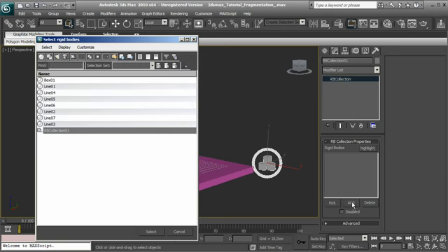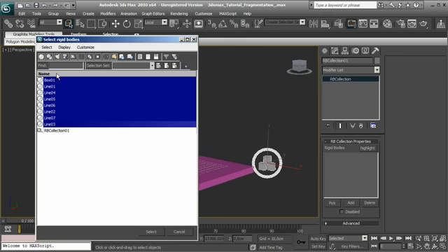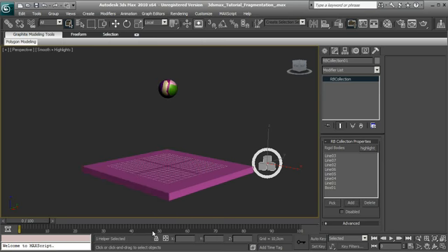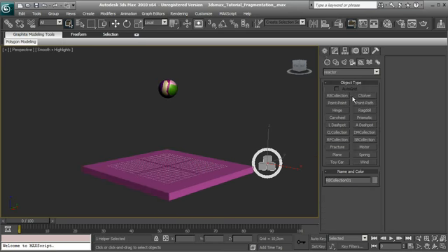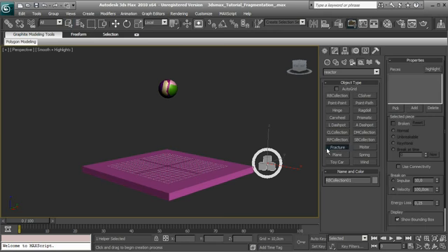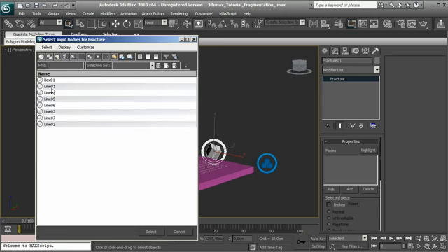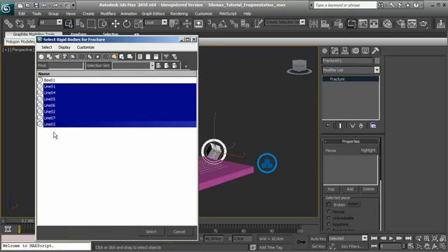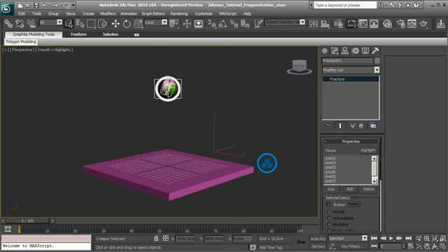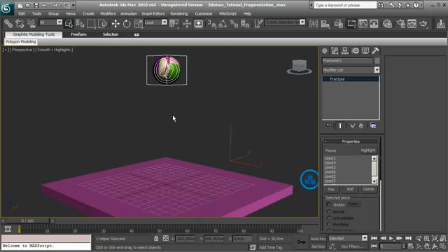We click on add, and we select all the mesh, so all the pieces and the box. Select OK, and now we have to create the fracture mesh, so we select fracture, we create it, we go in the modify, and we select add, and we select all the pieces coming from the original sphere, and you can see that now we have the fragmented mesh.